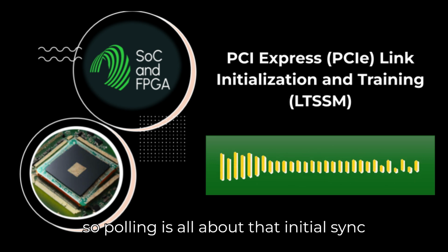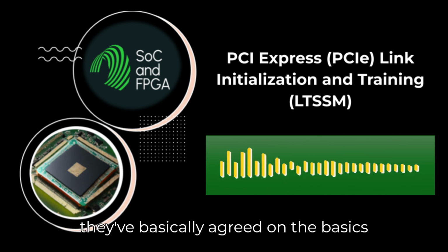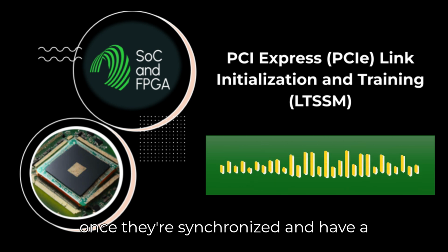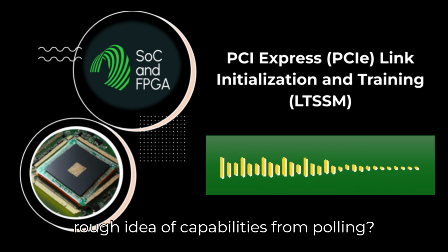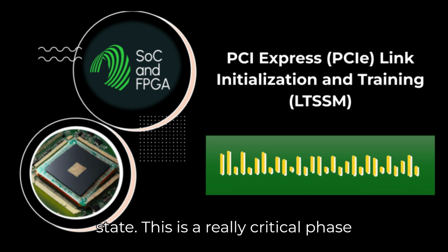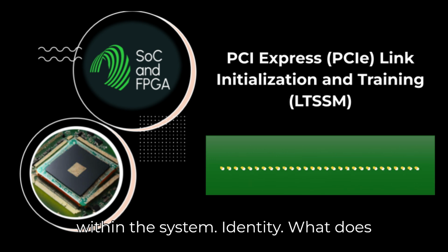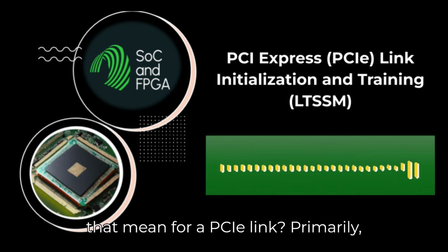Okay, so polling is all about that initial sync up and capability swap. What happens once they've basically agreed on the basics? Once they're synchronized and have a rough idea of capabilities from polling, the LTSSM moves to the Configuration state. This is a really critical phase where the link gets its unique identity within the system. Identity. What does that mean for a PCIe link?